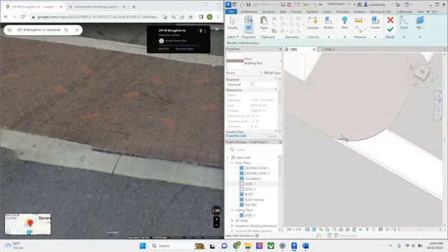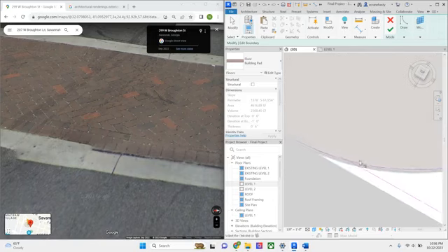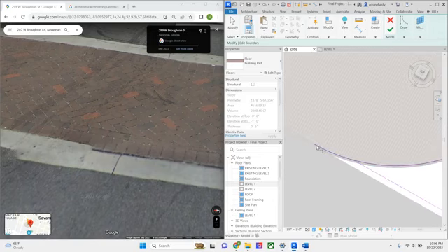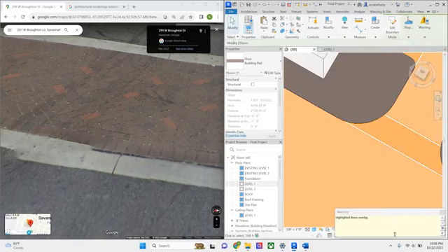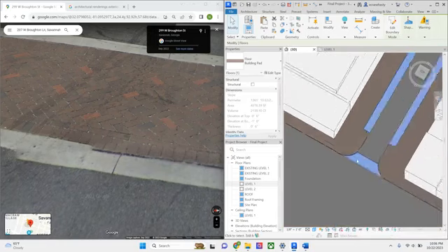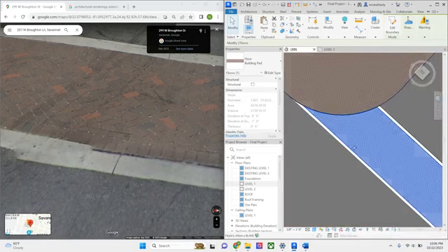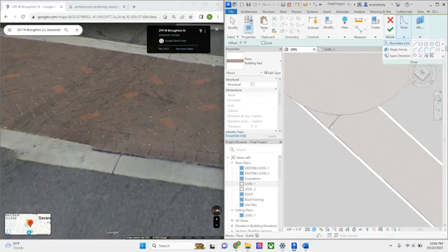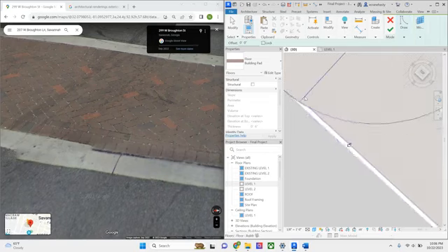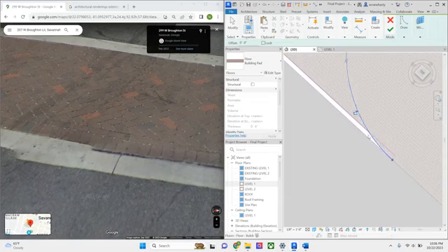Oh, there it is. When it doesn't give you that error, it just means that there is a rogue line. So notice how that end is over here and this end is right here. They have to be a closed shape. Hit OK. Floors overlap. Yes, I know. And now I'm going to create a similar guy. Use my pick lines and just go and pick lines.